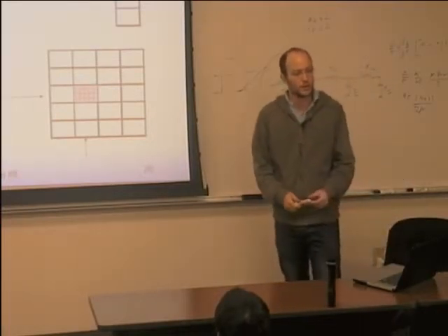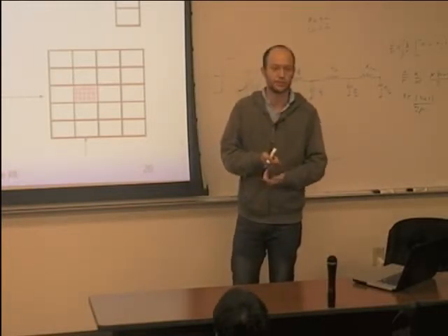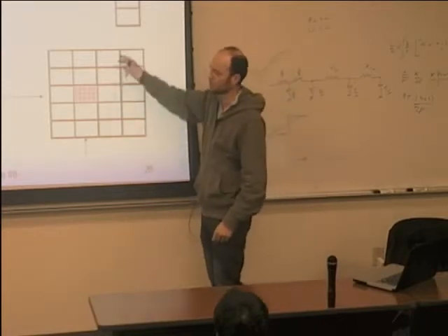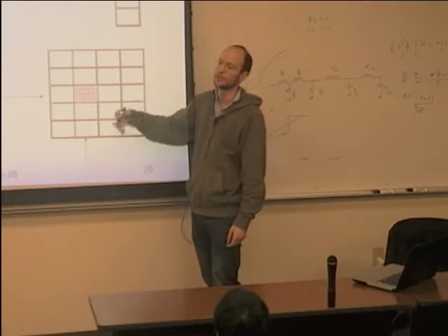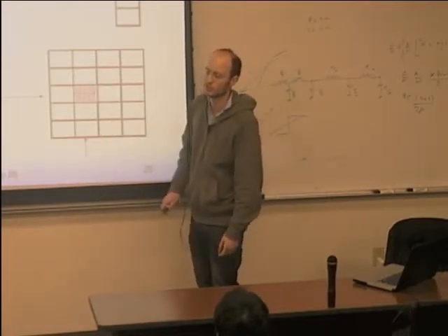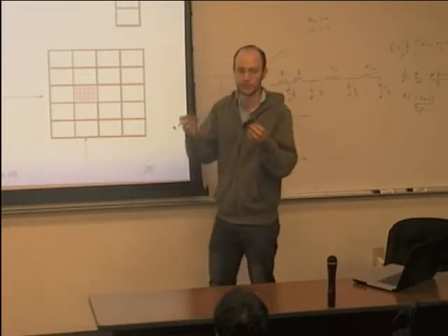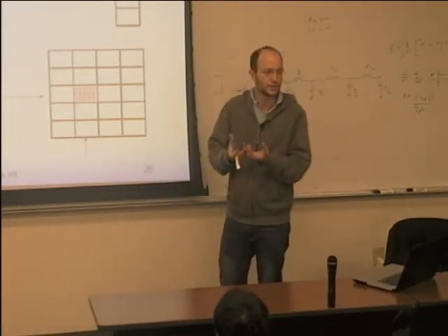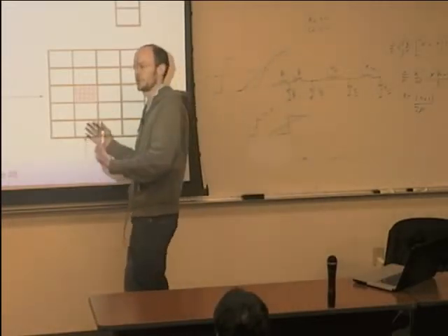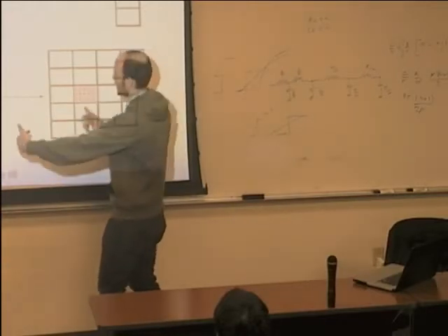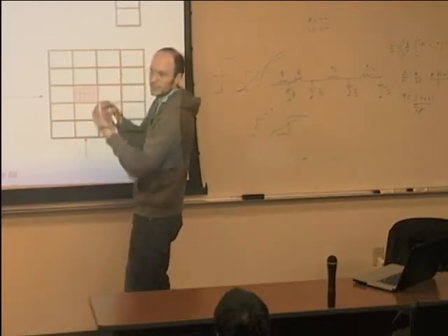Okay. Then what I'm going to do is I'm going to provide the memory an address. So I'm going to say I want to write, so there is 1 million cells, right? And I'll say I want to write a 1, for example, in the cell number 384,000, okay? So now I need some logic that takes this 384,000, which is some binary number, okay? And converts it into what's the row corresponding to 384, it selects this row, and then it selects this column, okay? And this cell is exactly the 384,000.